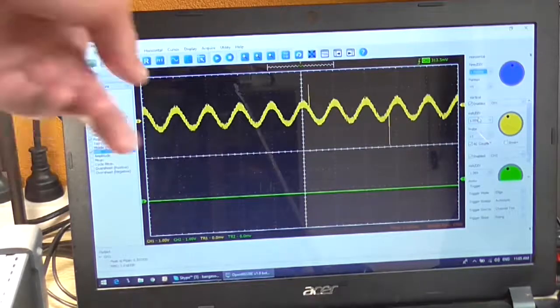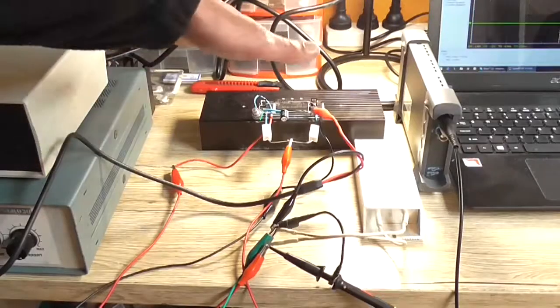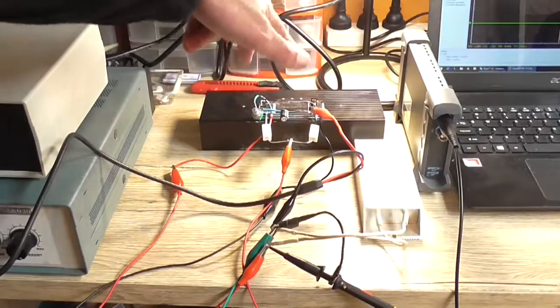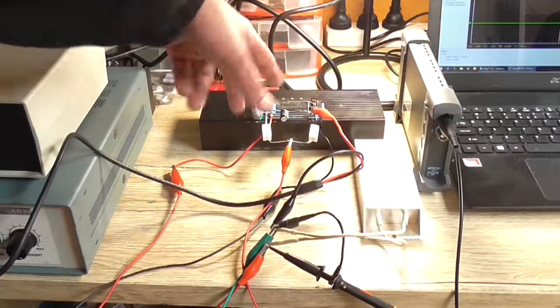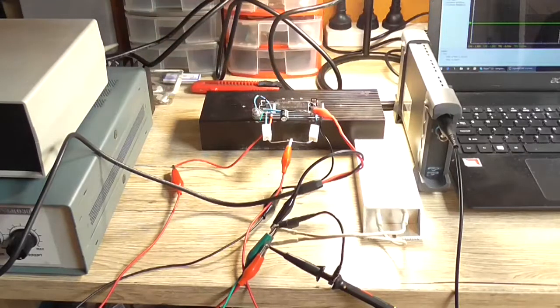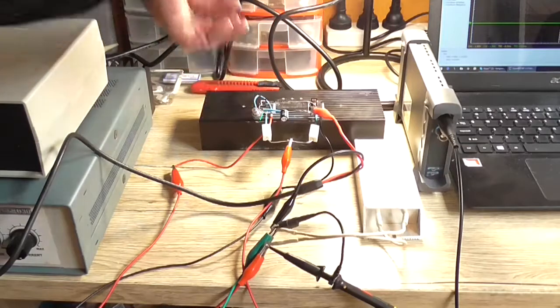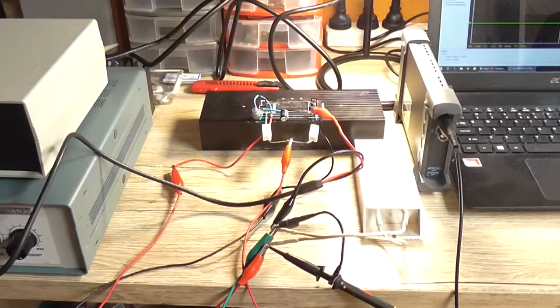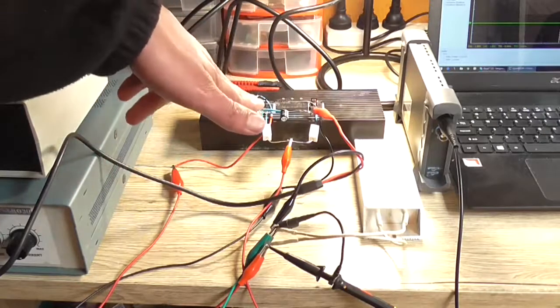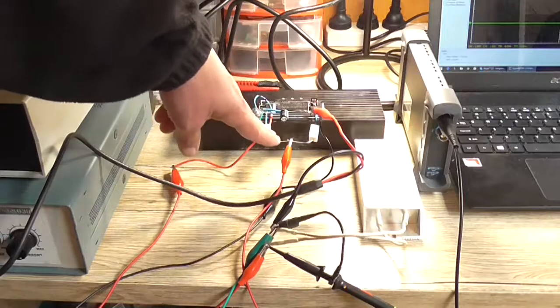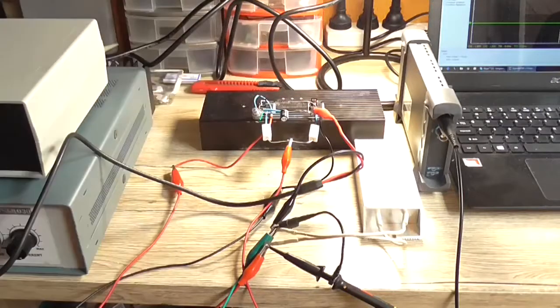But why is it ringing like that? Well, the simple answer is because the CFP, or the complementary feedback pair, are good for producing high gain, but they're very susceptible to going into oscillation. They're unstable, and the reason why it's probably not stable at the moment is because there's no Zobel network in the mix there.